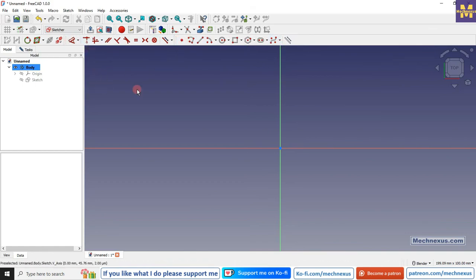The Sketcher Workbench features constraints, allowing 2D shapes to follow a precise geometrical definition in terms of length, angle, etc. A constraint solver calculates the constraint extent of a 2D geometry and allows the interactive exploration of the degrees of freedom. Now let's understand what the degree of freedom is.